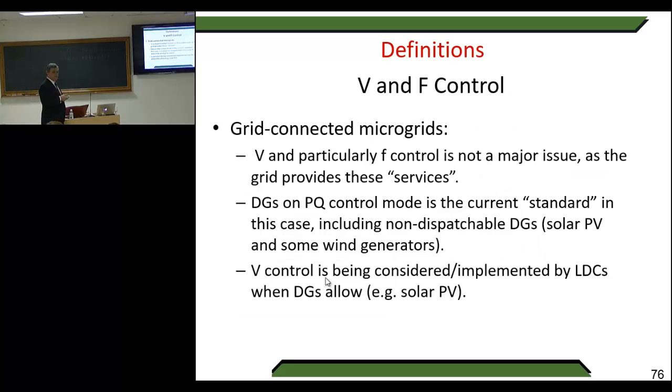Definitions: we have the grid-connected microgrids, which is one world, and we have the islanding or off-grid operation of microgrids, which is normally for us the worst case. Although you are analyzing a grid-connected microgrid in the islanding mode, you need to be very careful. All that you learn from isolated microgrids are inputs that are valid for connected microgrids, in our understanding, when they operate in islanding mode.